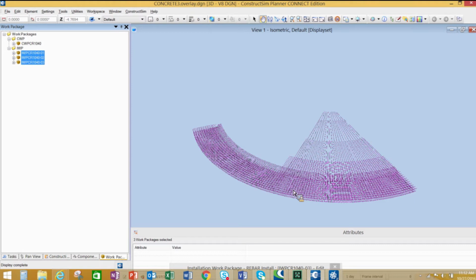I've used this particular process on a project that I did a year ago. In doing that project, we did not have to order any additional rebar. We did two things. One is we were able to have the rebar pre-bent and tagged appropriately to the foundation, so we didn't lose any of those rebar pieces, and also we knew exactly what foundation it was going to.